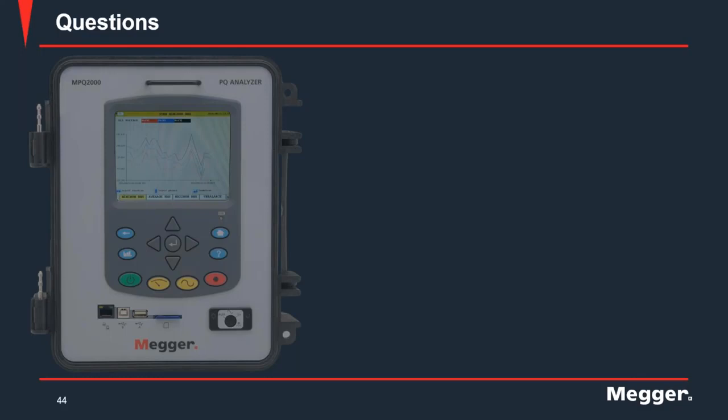If you are talking about data files, the data files will be created once the recording is complete, and the default name is tests followed by the number, and you can rename those on the recorder by hitting the scope mode shortcut key. The setup files can be renamed at any time. On the recorder, you will see the same rename option when you go into the setup file screen, and you can rename the setup files over there. So basically they can be renamed on the recorder.